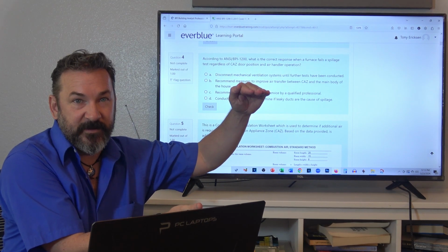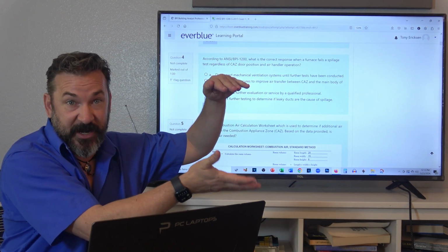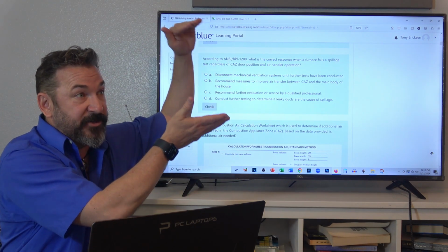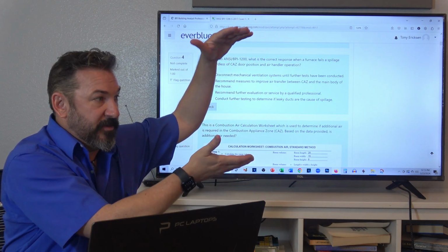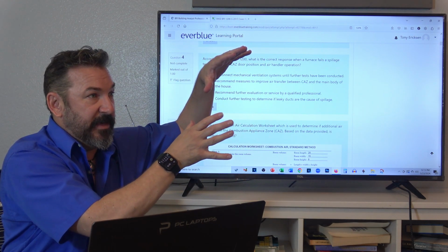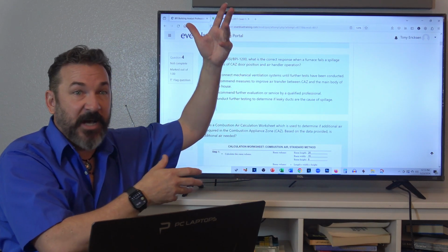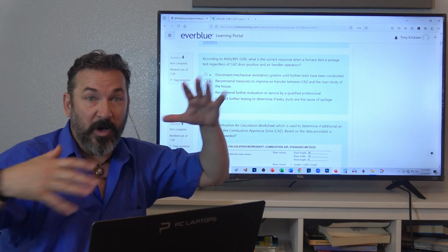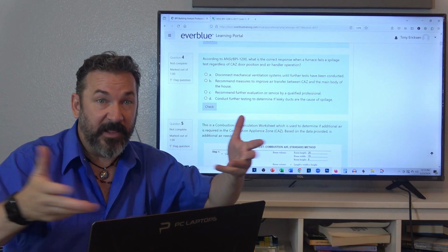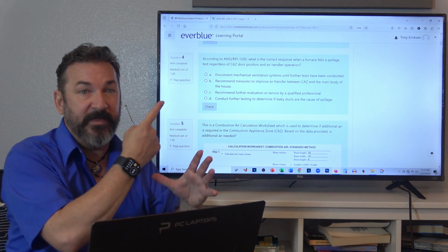In a vertical unit, the bottom section is the air handler, then there's the furnace section where all the burners and everything, the heat exchanger, are, and on top of that is the air conditioner. The heater and the air conditioner are what condition the air. The ducts, including the plenums and the returns, just distribute: they direct the air and collect the air, and the air handler, the fan, is actually what's moving the air.